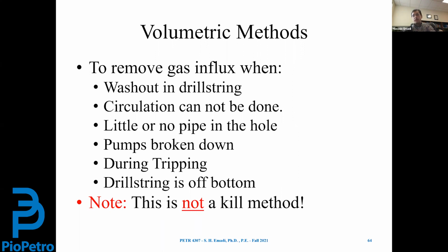the surface. However, if 1 gallon of gas enters the wellbore, depending on the pressure of the formation that gas is entering the wellbore from, the volume increases because as the gas moves upward and the hydrostatic pressure acting on the gas bubble starts to decrease, the volume of the gas starts to increase, provided that it's an isothermal condition. So hydrostatic pressure, which is acting on the gas bubble, decreases, the volume must increase. P1 V1 equals P2 V2.